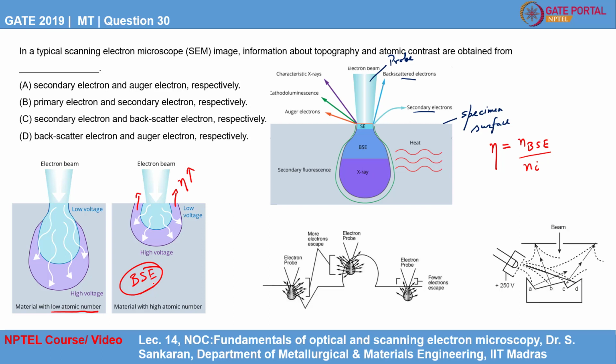Okay, this is shown in this particular image. This is the trajectory effect. So surface B and surface D are facing the detector, so the electrons emitted from these surfaces will be collected by the detector easily, while on the other hand, surfaces A and C, which are facing away from the detector, will appear darker because electrons will have difficulty reaching the detector. The next effect is the electron number effect.